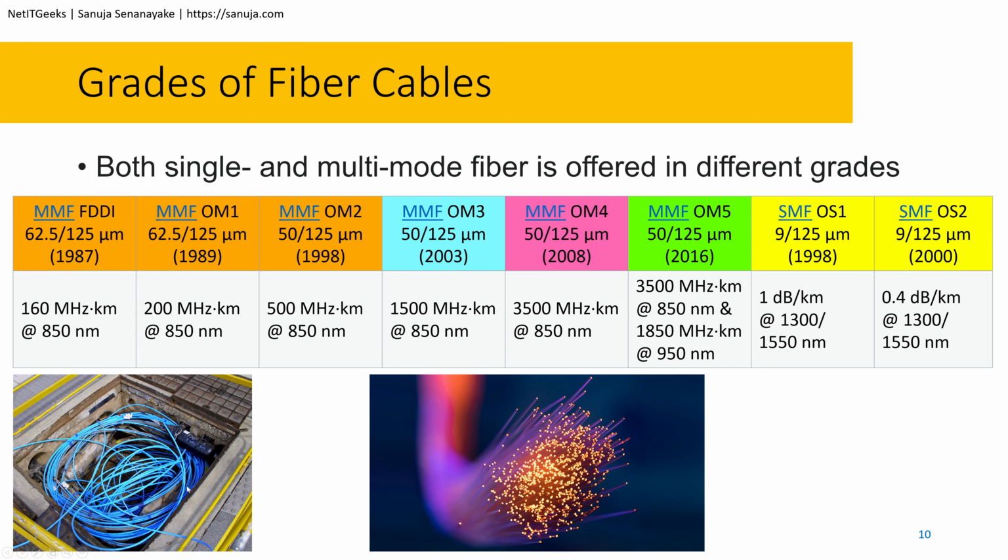And here is a picture of a fiber optic communication cable in an actual installation setting. This is a real cable and what it looks like when you have communication going through. But keep in mind, not all light is visible, and not all visible light is used for fiber optics communication. That's why there are some safety concerns you should take into account when you're working with cables that you believe are turned off. You should never look directly into these, for example. I will go over that in the next few slides as well.